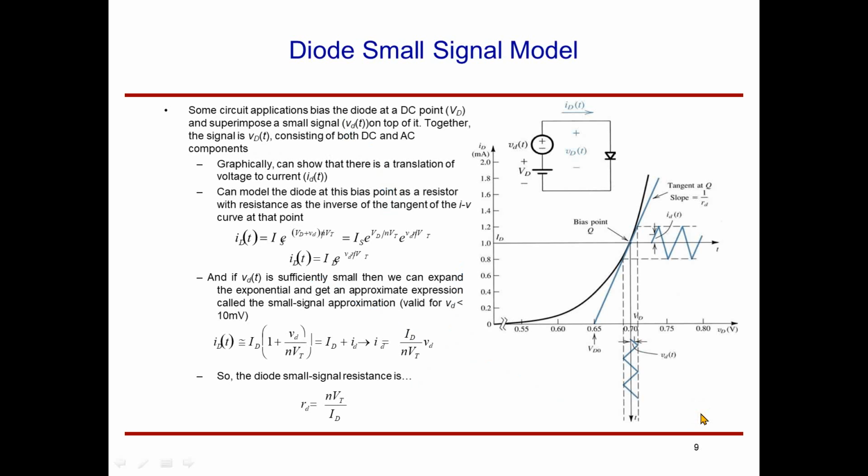Coming to the diode small signal model. In the diode small signal model, we consider the basic diode current expression. With that expression, we look at the slope of current and voltage, because on the x-axis we have considered the voltage and on the y-axis the current. While taking the slope, there will be some change in the voltage and also some change in the current. That is the major point for calculating the resistance R as V by I.